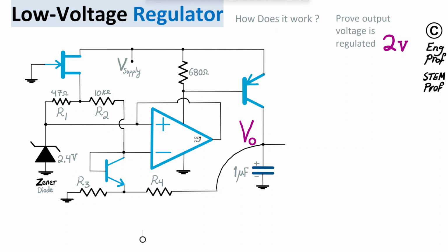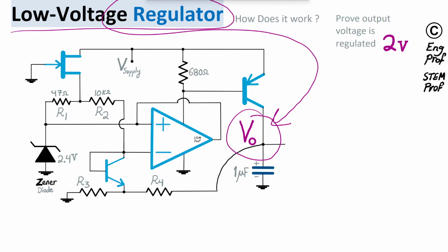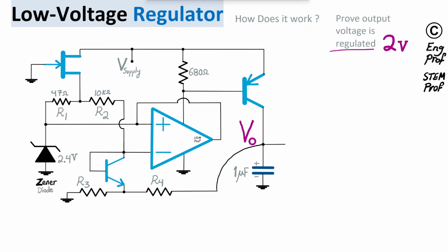How to design a low-voltage regulator is discussed in this circuit design example. The output voltage of the regulator is shown to be a regulated 2-volt output, so that when we connect a load RL as shown, we have a fixed 2 volts across that load. That's a low-voltage regulator, and the maximum current we can provide to the load depends on the high-current PNP Bipolar Junction Transistor that we select in this circuit, shown as transistor T3. So the choice you make for this one defines the max current of the circuit.